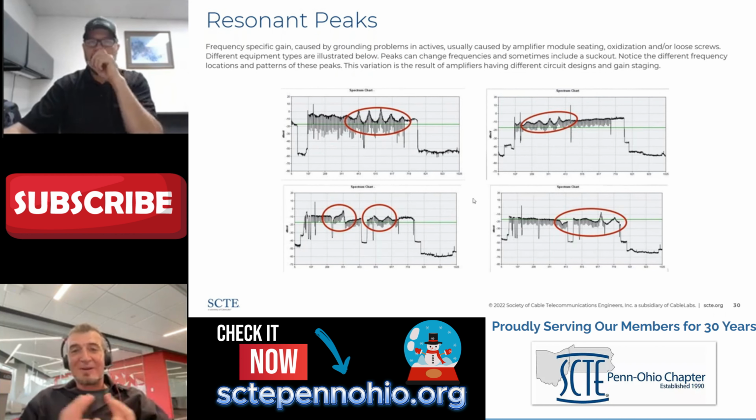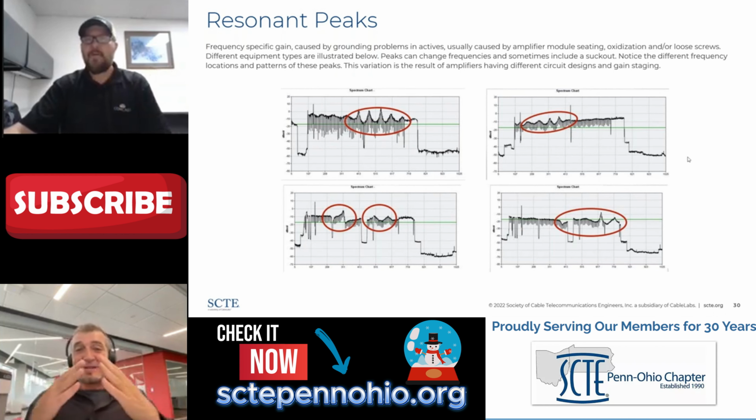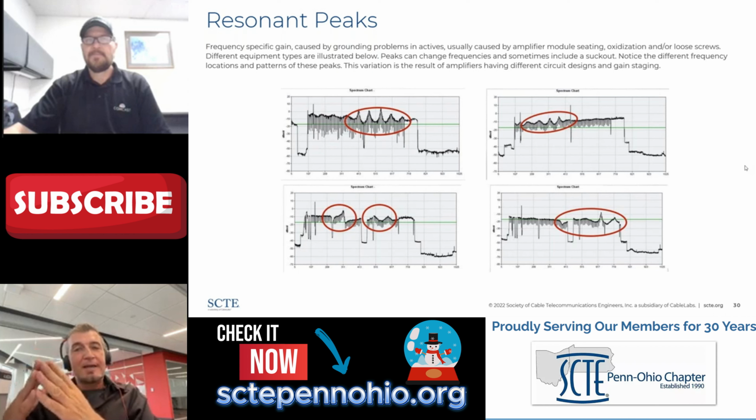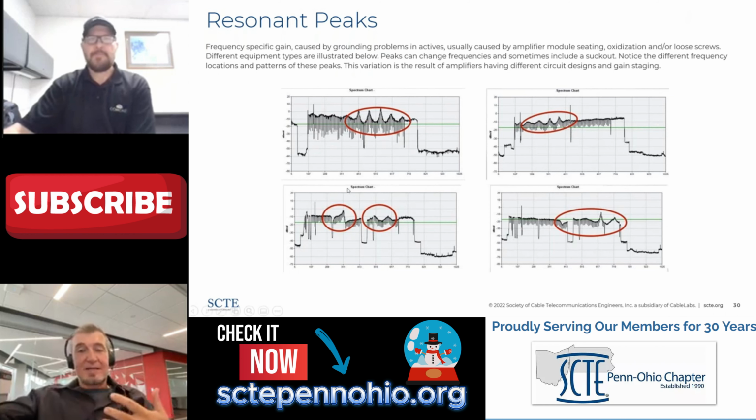Yeah, I did want to pause there for comments on that. Let me jump in really quick. There's two things. Resonant peaks, just like suckouts, have different amounts of severity, but if the peak is peaking on the ALC pilot, then you have the same phenomenon where you have the cascading effect. What could be a kind of minor thing, 5 or 6 dB of peaking at a given frequency, okay. But then if that is having this cascade effect on your amplifier performance and distortion and compression, these other things, then you might have a real problem. So pay attention to this.